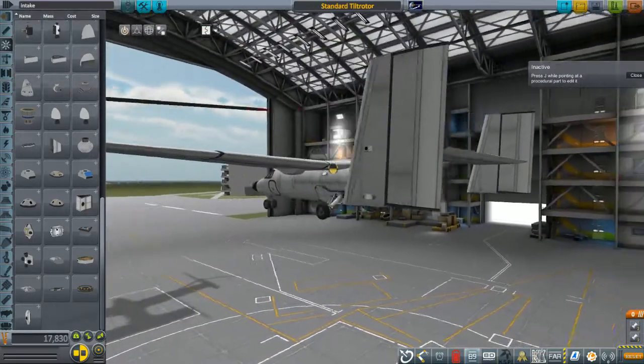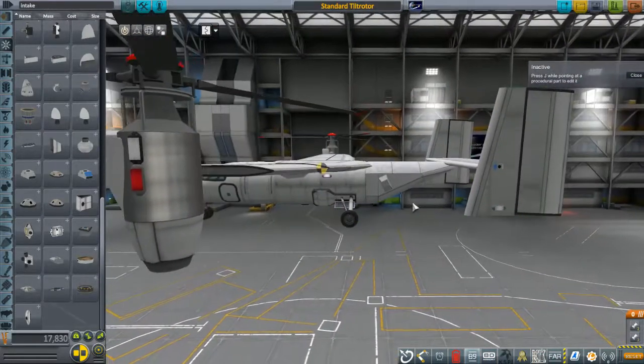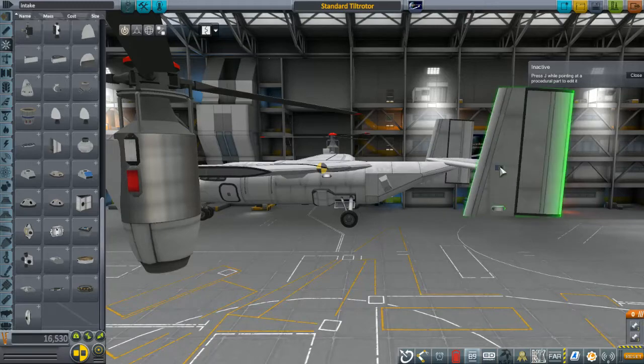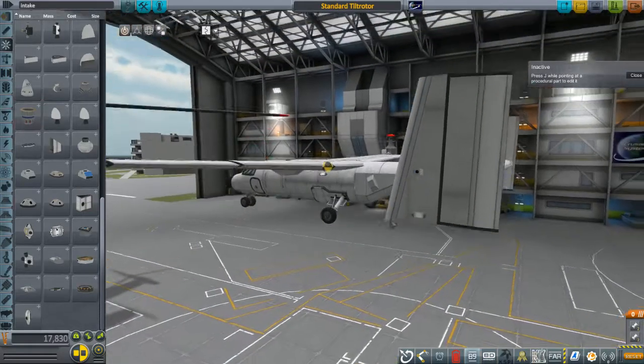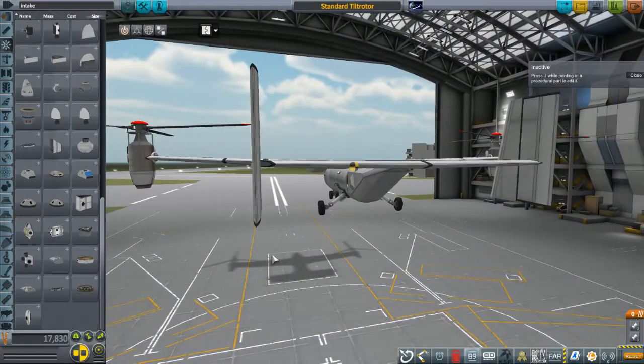And of course you want to get these maneuvering thrusters as close to your center of mass on the non-active axis as possible. So in this case, they actually do need to be kind of up here, but not like up here on the tip of the vertical stabilizer, otherwise it's going to try and, for example, trying to yaw left, point your nose further to the left, that would actually try to roll you right if it was way up there and above your center of mass, because it would be acting like a fulcrum in the vertical plane.